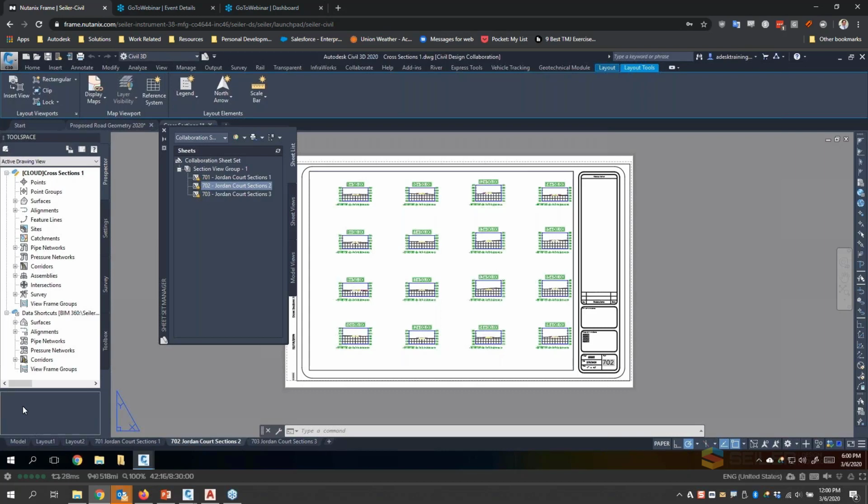This 2020.3 update has really gone ahead and fixed some of the major problems that we had at the original outset of it, and we only hope to see it grow more from here. I don't think there'll ever be any kind of, multiple people being able to work on a single drawing. That's just the way AutoCAD files work. They're not set up for that type of functionality, but follow the same rules you're using now. Multiple drawings, again, several small drawings. Use data shortcuts. Use XREFs to bring those across.